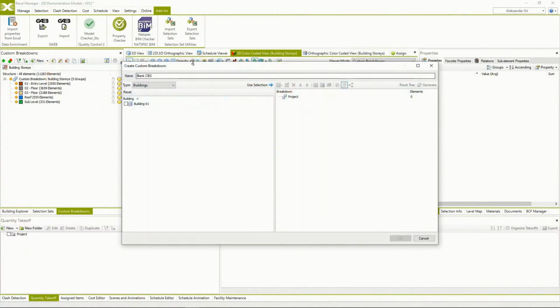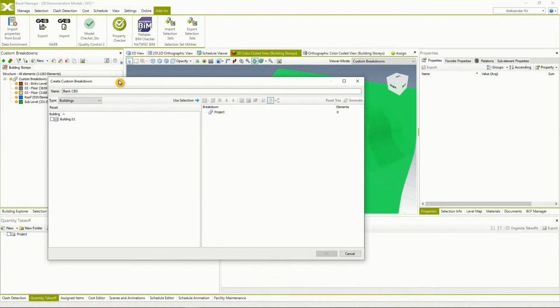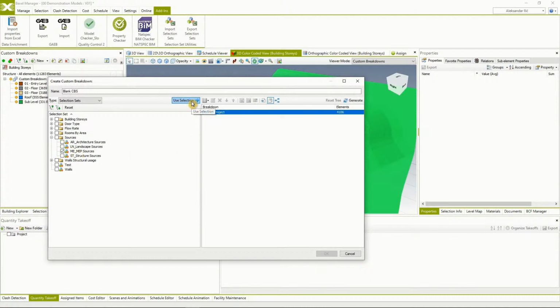So let's say that an MEP system color coding template is present. That means that you have a certain standard for how you color code MEP systems on your projects. So it colors different system groups according to predefined standard rules. Such rules could be defined at a company level, team level, and so on, or could be part of market requirements.